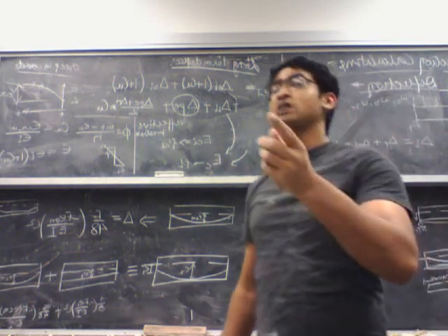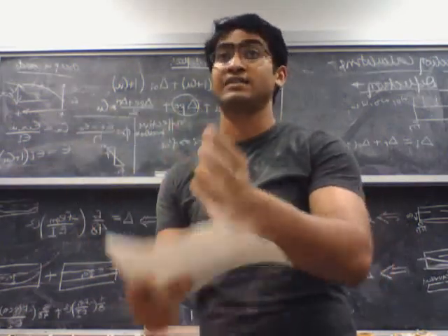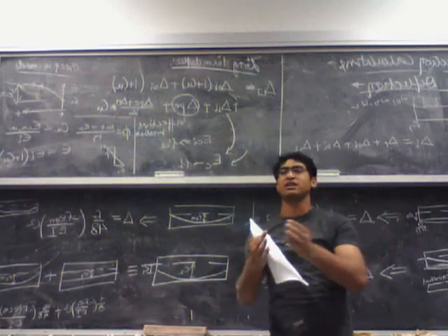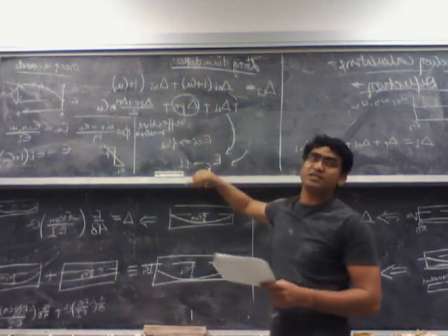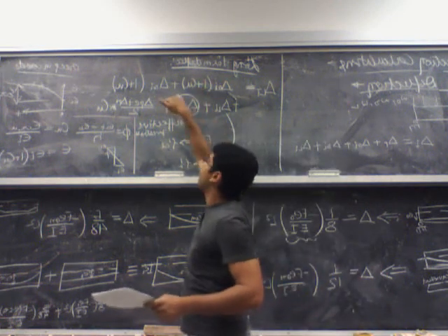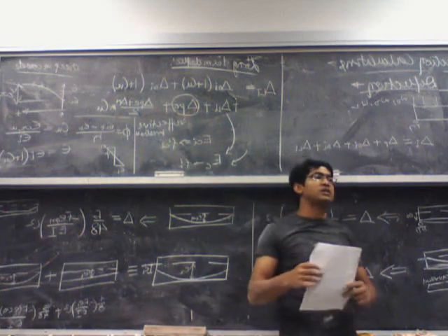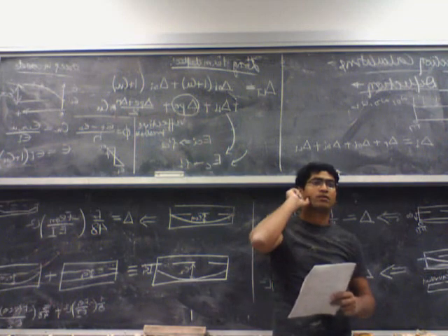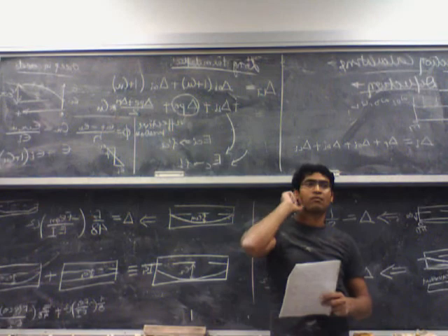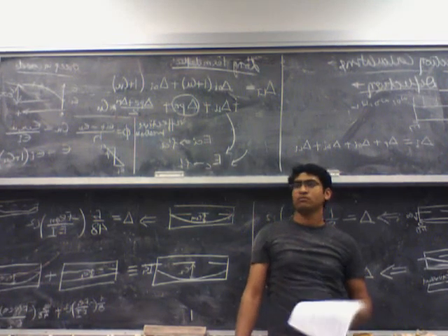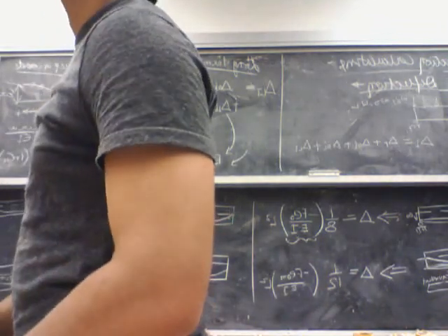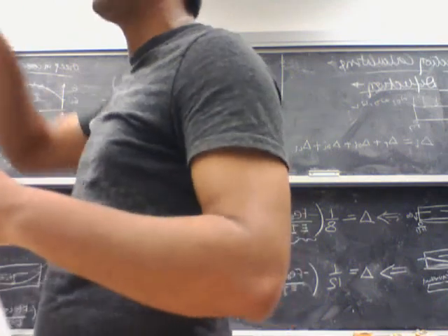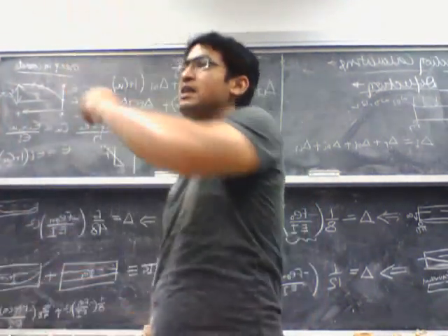Yeah, because it is assumed that both the dead and the live load are applied at service condition, right? And you also assume that at service condition your concrete has already gained all the strength it has to gain. So for Di and Li you use Ec, which is based on f prime c. And for delta Oi, delta Pe and delta Pi you use f prime ci, because these loads are applied right from the very beginning. You'll use the f prime c for the dead load and the live load. But for the other three cases, which is delta Pe, delta Pi, and delta Oi, you use the f prime ci to calculate your E.